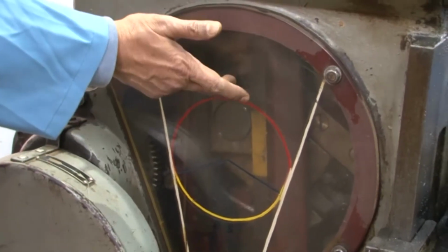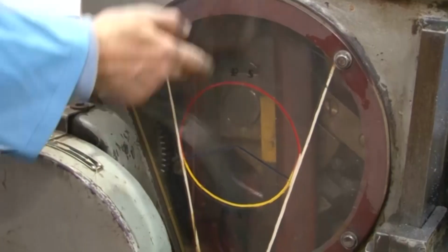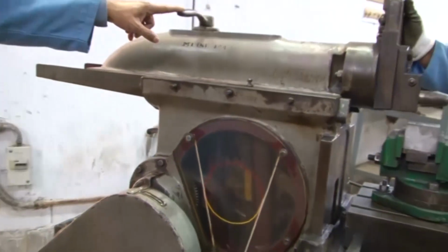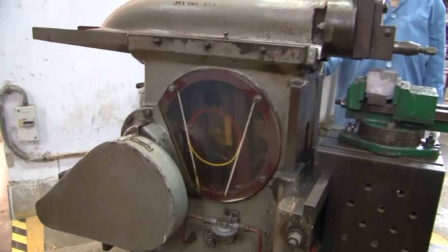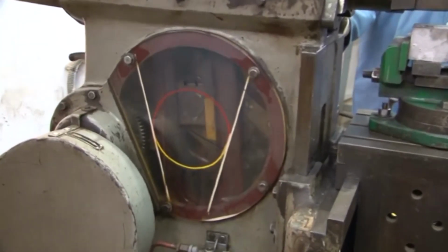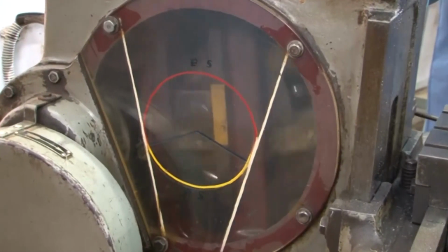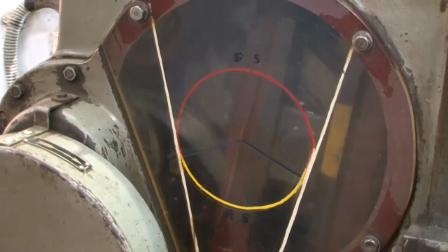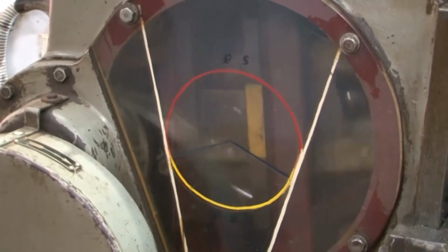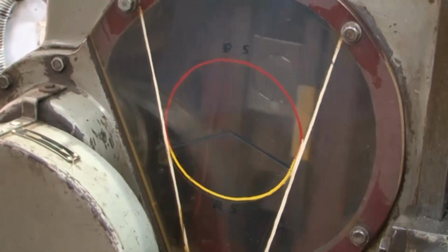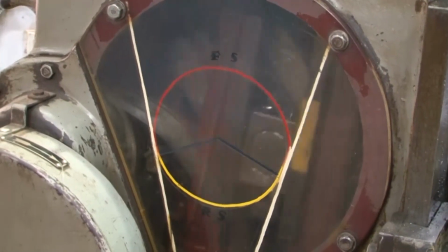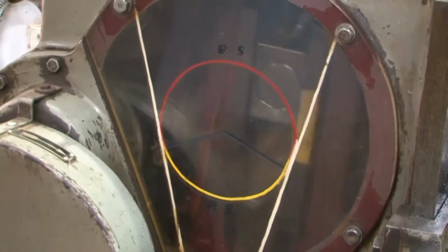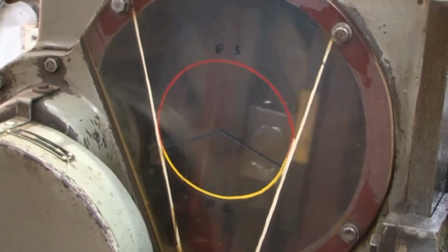So, we will show you how that speed can be changed by changing the arm length. Now, you have seen that this is being changed. Now, the arm length has been changed, and if we switch on, you can see that the stroke length has been increased. Okay. Tool is coming up to here. Yeah. So, you can see the stroke length has been increased, that means bigger lengths of surfaces can be machined. So, that can be done by changing the arm in the mechanism, as we can see.